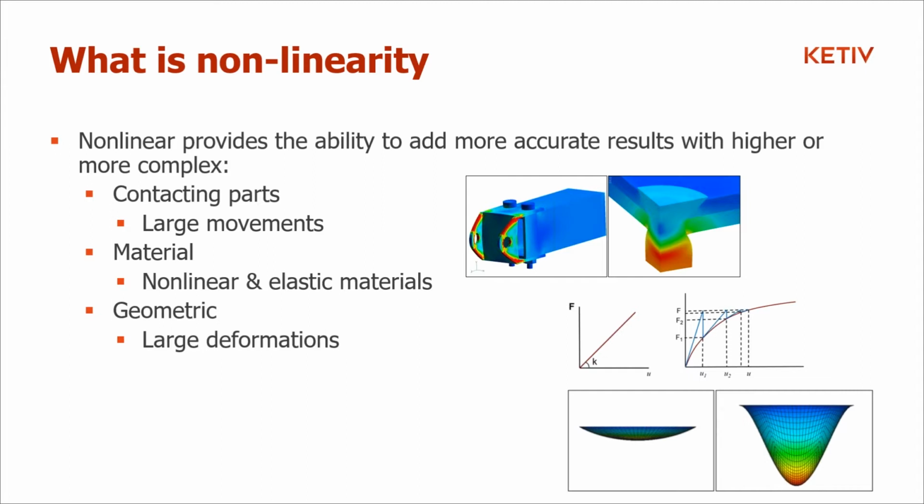Material is the most obvious one, probably, right? The nonlinear materials such as plastics or rubber. What that really means is when you go beyond the yield or the ultimate strength of the material itself. So if we are going beyond that with metal, then that's technically nonlinear. And maybe another way to explain it is, when it goes beyond its yield, it doesn't necessarily break. It just might not return to its original form. So if you have a piece of metal that you're bending, then it's no longer going to go back to straight. It's going to stay bent over, right?